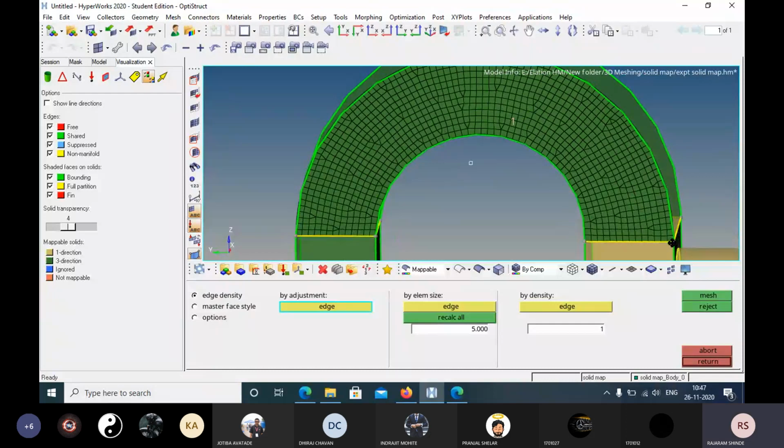And it will change both sides. You can see here now you will not get any triangle in this direction. Now here there is one triangle. It is on this side. Now here you can check the number of elements. There are 14. Here you can check there are 13. I will increase one by one. Now you can see here all triangles are removed from here. Now this 14, when we adjust, it will move to this 14 also. That means this number and this number will be same if it is a proper geometry.